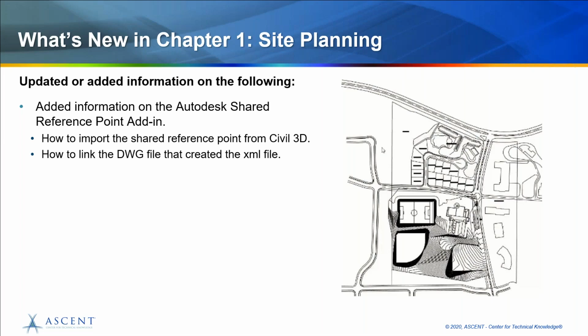With that being said, it is always important to know how to utilize and work with Revit shared coordinates. Even though I have utilized this add-in before in projects, it was still crucial that I understand Revit coordinates and how to share and publish the coordinates properly. And as with all add-ins, they are typically upgraded to the next version last, so we should never truly rely on them. But this one seems to have a long history, and I'm really surprised it hasn't been incorporated into the software as a tool that you don't have to install.